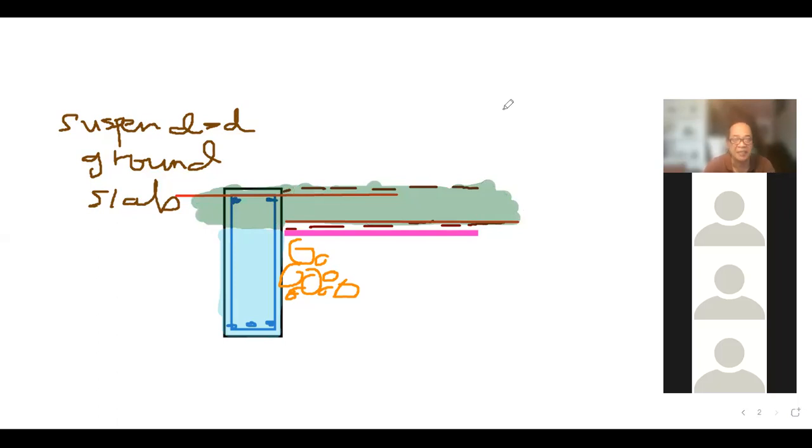So I have a two-stage concreting technique. The first stage is that the ground beam is concreted. Pouring of concrete is until the soffit of the ground slab, then the stop, and then all these hardcore and the sand blinding layer is put into place, and then the reinforcement for the ground slab located di sini, indicated di sini, and finally this would be my second stage concreting. Second stage. Previously this was my first stage. This was the first stage punya concreting.